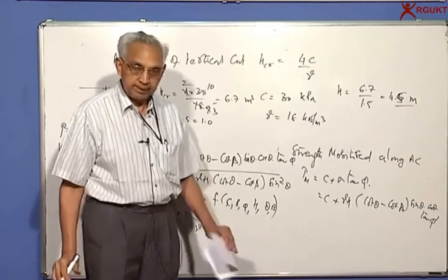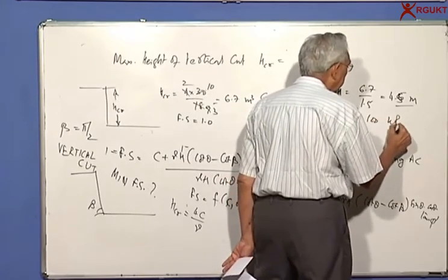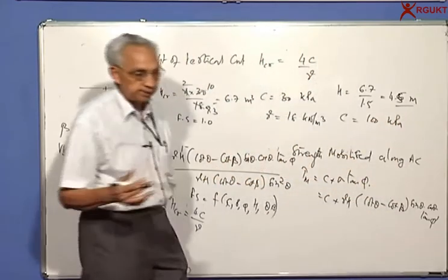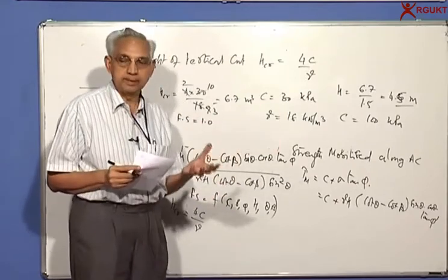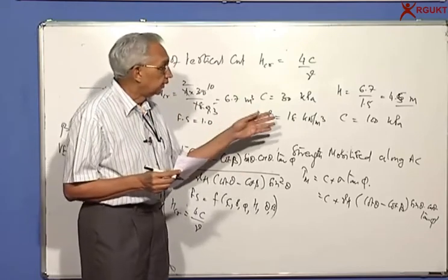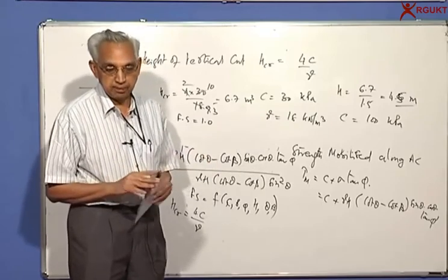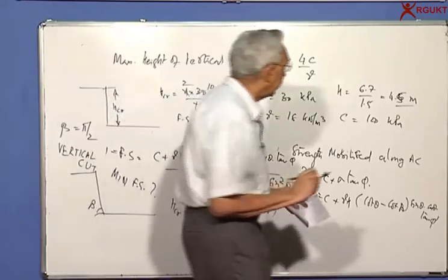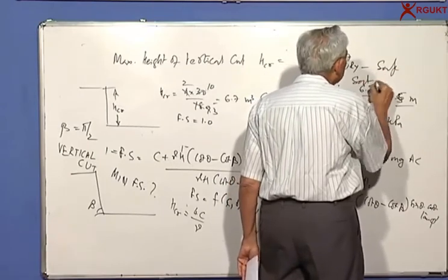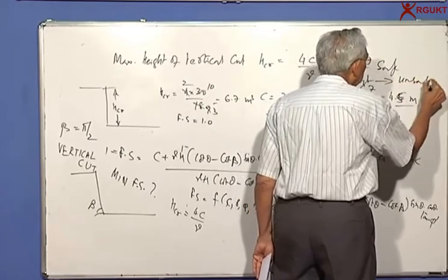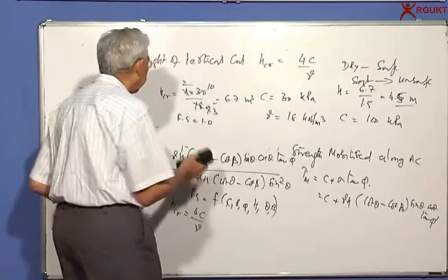That may be. Whereas in Hyderabad, you can get C of the order of even 100 kPa, which means you have no problem. Most of the time, the cuts can be very deep, provided there is no water. We have derived in the last class that if it's saturated, the strength reduces and the factor of safety becomes very small. So in dry condition, safe, but if it is saturated, it may become unsafe. That is why you find a lot of failures taking place during rainy season.